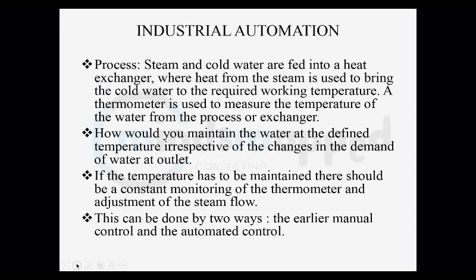Now, how would you maintain the water at the defined temperature irrespective of the changes in the demand of water at the outlet? I just explained how we are going to do that, yes? Right. So if the temperature has to be maintained, there should be constant monitoring of the thermometer and adjustment of the steam flow, which is what our manual operator is doing there.